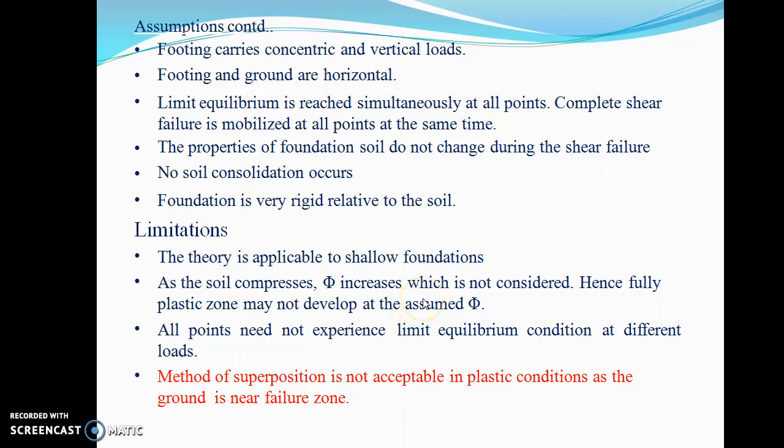Properties of foundation soil do not change during the shear failure. Usually what happens, if something is settling initially, then it's likely that after a certain amount of settlement, the soil layers right below are going to get compacted. So the density and all these parameters will change after the initial stage of settlement. But we do not consider that.